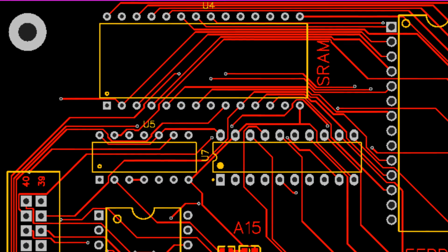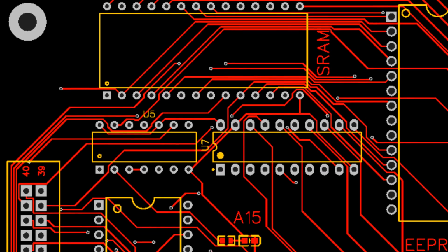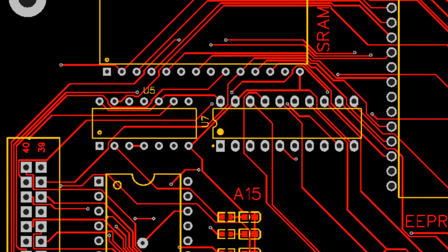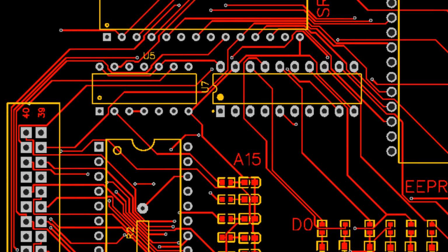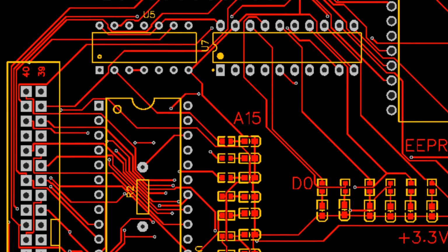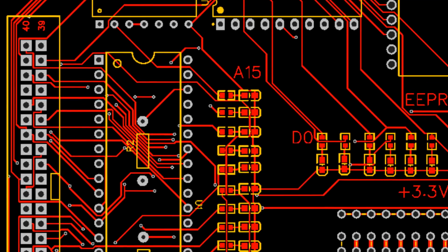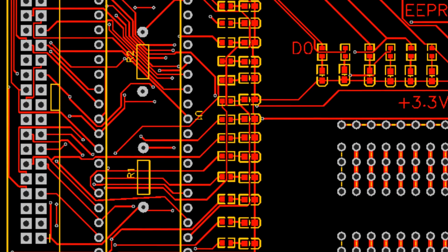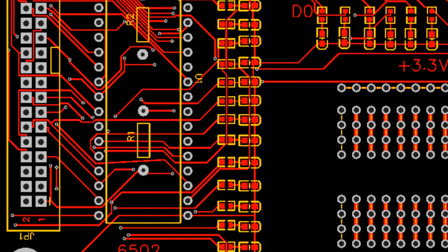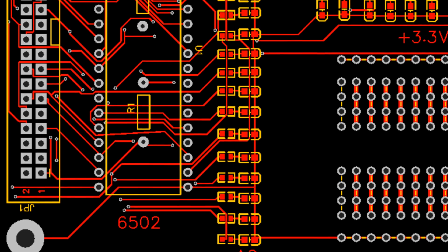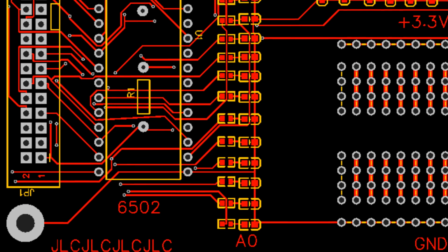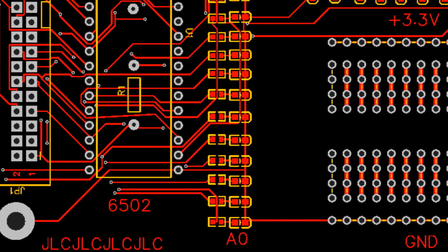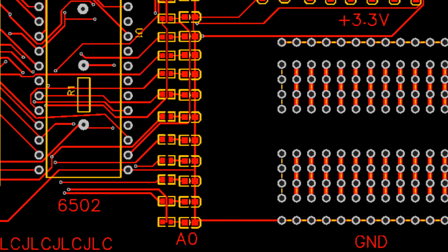To tell you the truth, this is the first PCB I have ever designed, and what you see right now is its first iteration. As you can imagine, there are a few flaws. The biggest of these flaws is that I assumed that when the ROM and RAM are in a high impedance state, that is to say, when neither of them are outputting data through their pins, the bus transceiver would be in a high impedance state as well.